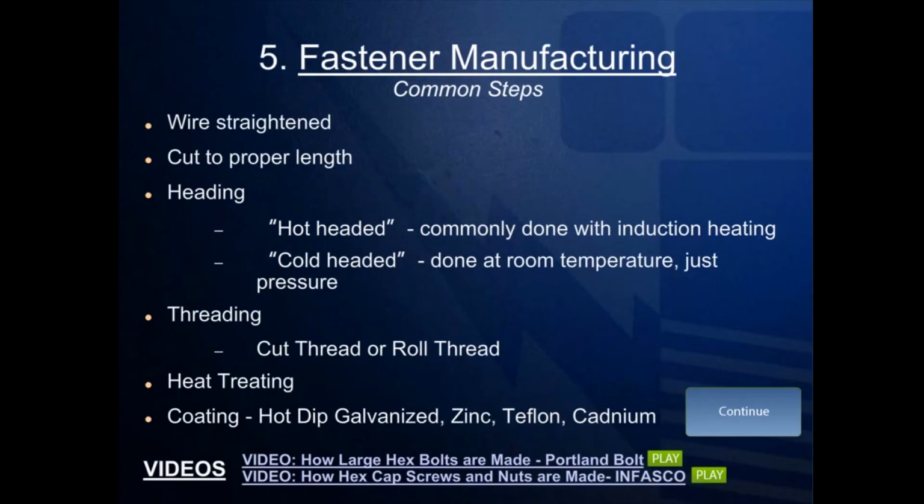It is often helpful to understand the processes required to make fasteners. One of the first steps involved is to obtain the properly sized raw material. Then it needs to be formed into a shape, which is most commonly done by hot forging or cold heading. In hot forging, a piece of material known as a billet is heated, usually by induction heating, and then placed into the forging equipment once it is glowing red.